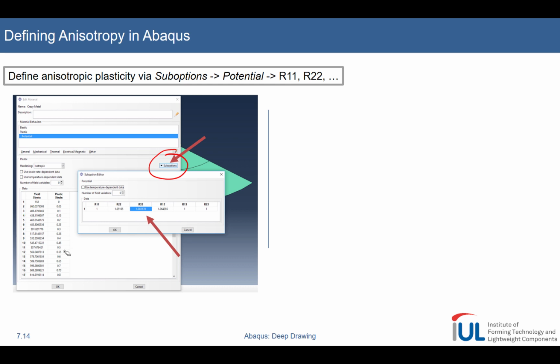values. However, as you can see here, check the first 2 values. Going from 0 strain, where initial plastic yielding starts, to 0.05 logarithmic plastic strain, we see the stresses more than double. So between these 2 points, Abaqus will do a linear interpolation.